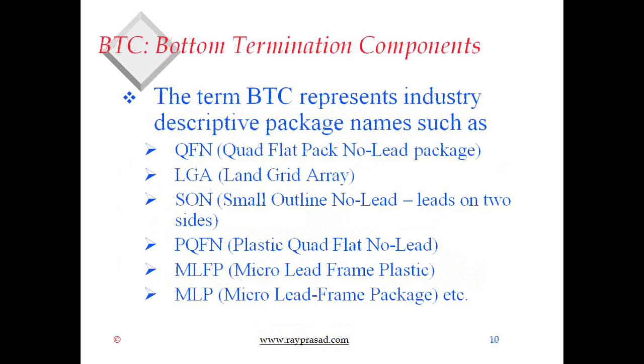On slide 10 here, there are a lot of names that are used for BTC. When I had my first meeting to start this committee, a couple of years ago, we spent half a day just to come up with a name that would be appropriate and cover all these kinds of devices like QFN, quad flat pack no lead, land grid array, small outline no lead, SON, PQFN, which is what Motorola calls their package, plastic quad flat no lead, micro lead frame package.